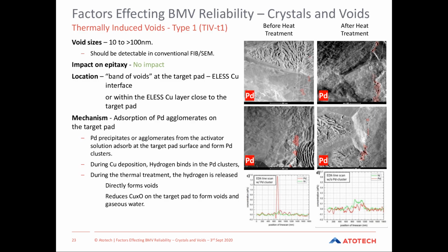The first one is one that we class as thermally induced because you cannot see it immediately after plating. So post-plate, the structure looks perfectly good. If you then go through some form of thermal heat treatment, whether that's a reflow cycle, a pressing cycle, or just thermomechanical testing, voids become apparent.